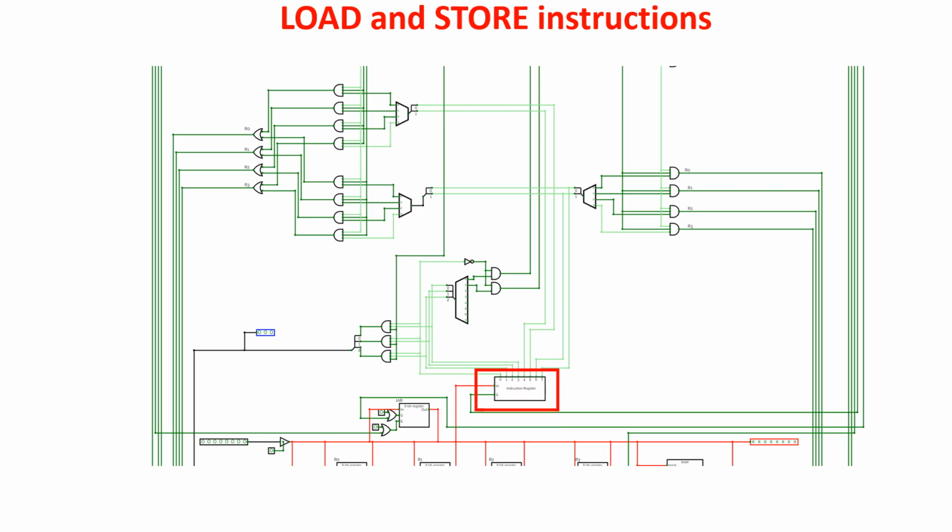Here you see the instruction register. In Scott CPU, the instruction has 8 bits. If the first bit is at 0, we have an instruction different from the ALU instruction we have seen in past videos. The 3 bits from the second to the fourth tell us what kind of instruction we have. So for example, this instruction says load the content of RAM in the RB register, the address being in RA. In particular, in this case, the RAM cell address is in R1 and the register loaded is R2. So the opcode for the load instruction is 0000.